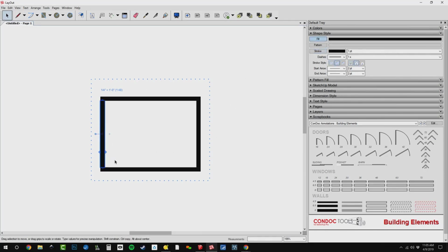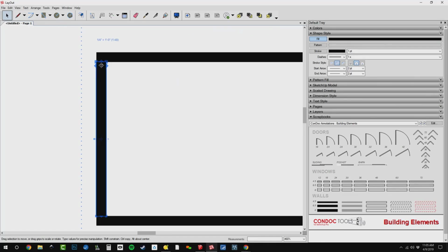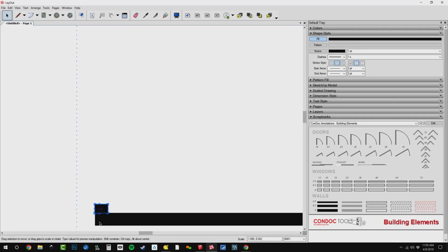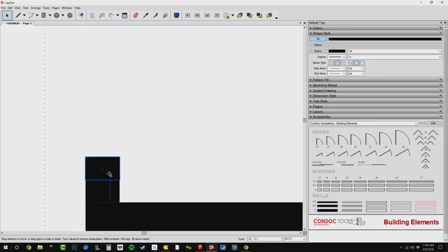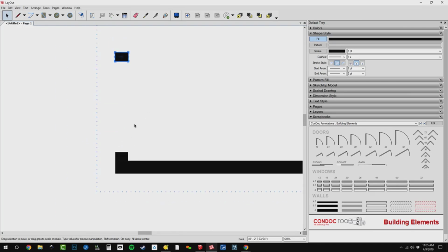All right. So let's keep going here. Now I want to put a door in right here, and we're going to put a window in here, and then tub, toilet. So let's do this. I'm going to stretch this piece down, and then I'm going to type in 3 inches, enter. And now that makes this chunk exactly 3 inches. I can make a copy of it and then move it again, and we're going to call this 32 inches, enter.